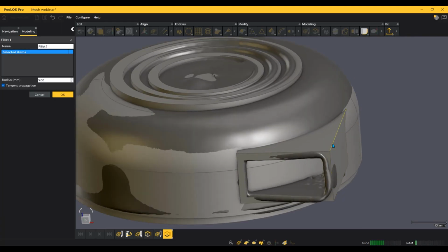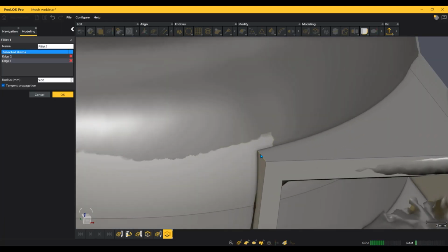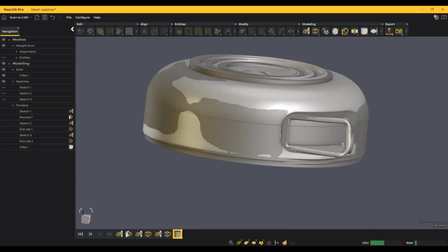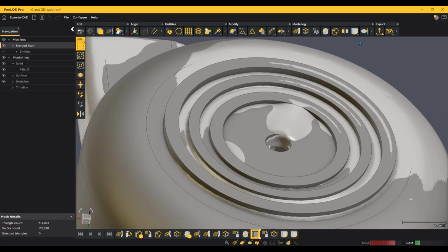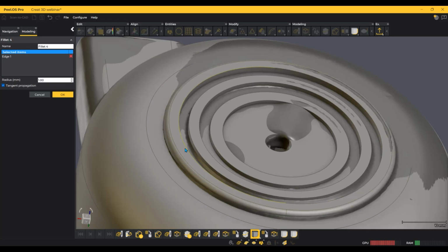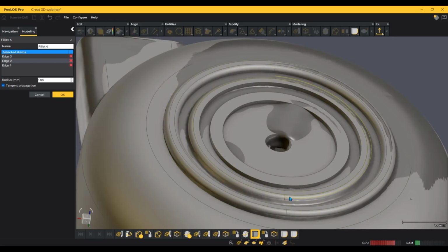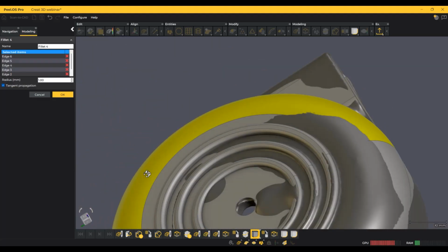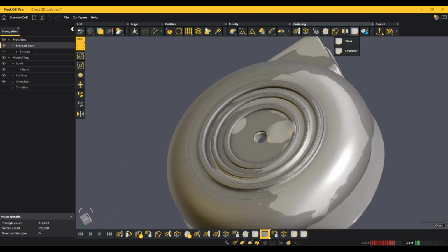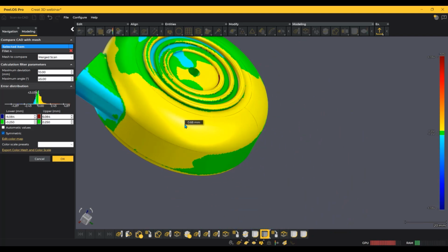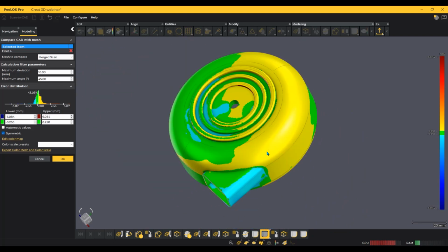With the reverse engineered model validated and refined, the next step is to export the CAD geometry for use in downstream applications. Peel.CAD Pro supports export to several industry-leading formats, including STEP. That is ideal for interoperability with most CAD platforms, and maintains solid geometry and parametric features. IGS. That is commonly used for surface models and legacy systems, and is useful for CAM and simulation workflows. DXF or DWG for 2D profiles and sketches, and is compatible with drafting and CNC software.